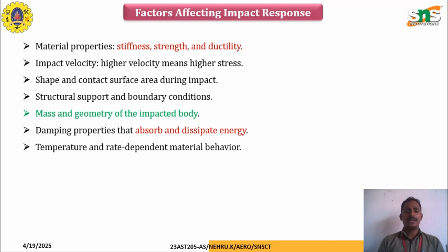A few factors affect the impact response. One is the material property: the stiffness, strength, and durability of the material determine the absorption of energy, which reduces or changes the impact. Impact velocity: high velocity means high stress will be produced. Shape and contact surface are other parameters affecting the impact response.